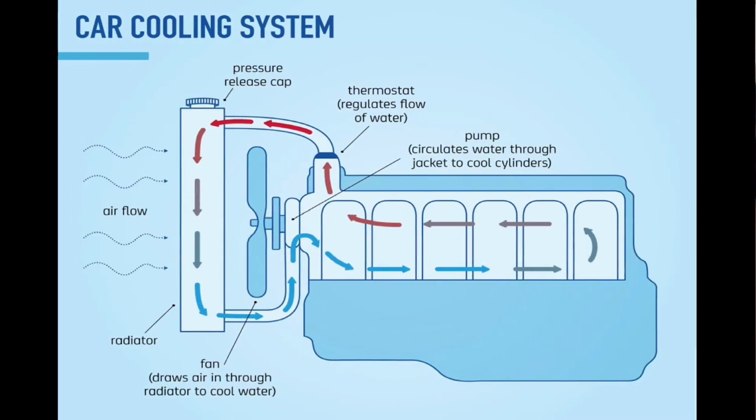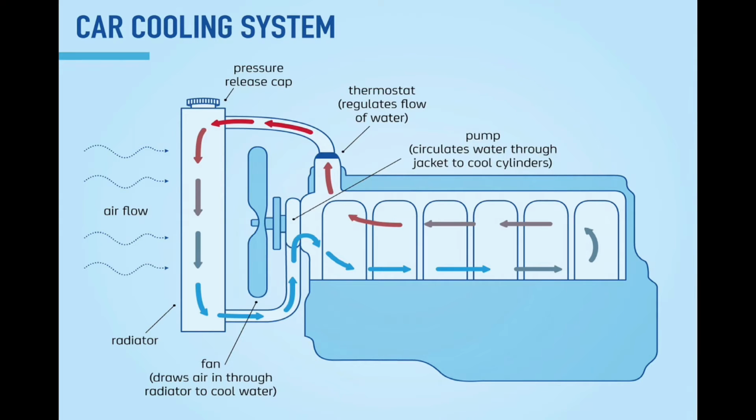So now I'm going to explain to you guys about water cooling system. Water cooling system is actually kind of related to the air cooling system. Let me explain the structure of the system. If you can see here, this is where the combustion happens and it will produce heat, and this is the heat that we need to remove. So, in order to do that, we have to flow cool water to surround the engine that will absorb the heat from the combustion to the water and be released at the radiator.